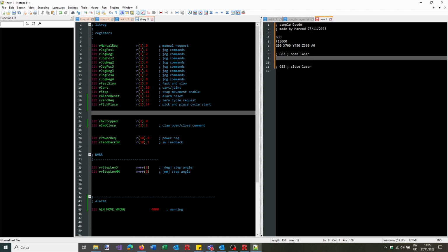So after we open this, let's say before this, we also would like another G00. We go down, so for example, the first could be Z560, and so here we want 360. So we go down, and then, for example, we can use relative coordinates and just say G01, and I want X, for example, 100. Maybe it's too much. Let's say X50.